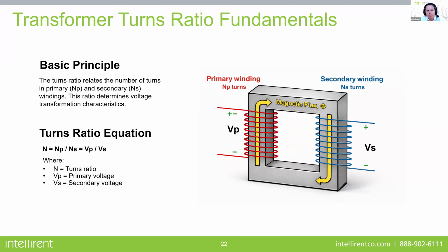TTR, where we inject a voltage on the high side of the transformer and you measure the voltage on the low side of the transformer. We're going to do that for A, B, and C phase, and also for the different taps.